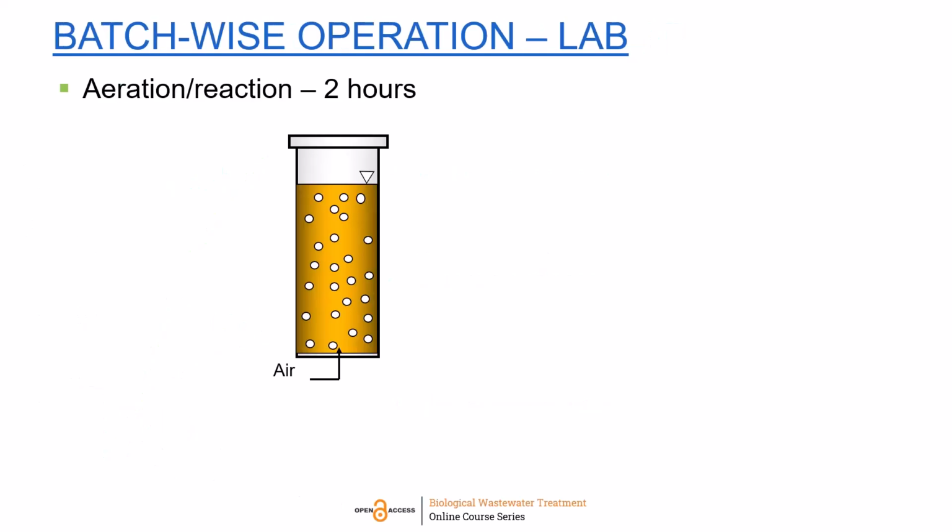Once the reactor has been filled with influent, the 2-hour aeration phase starts. Now oxygen is available for the aerobic microorganisms to grow. Given that there is little to no substrate left in the liquid, only those bacteria that have stored the substrate as storage polymers can grow.